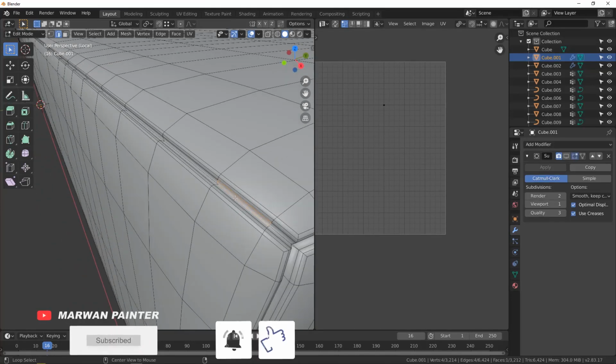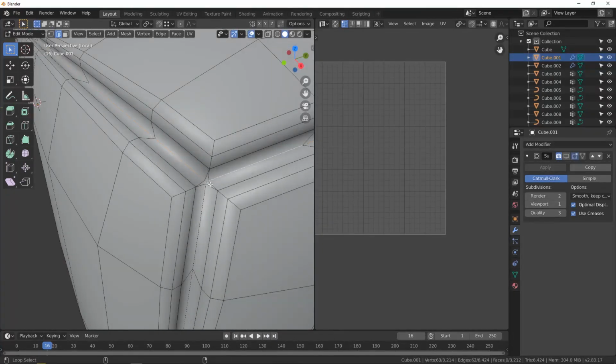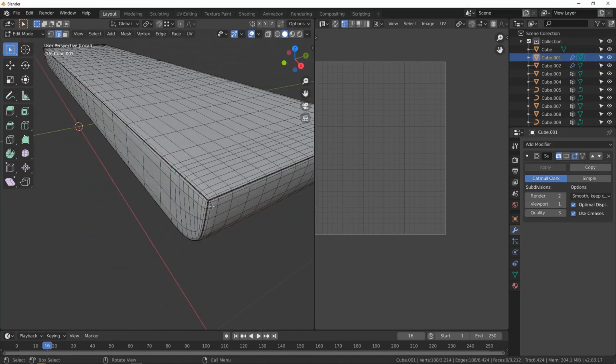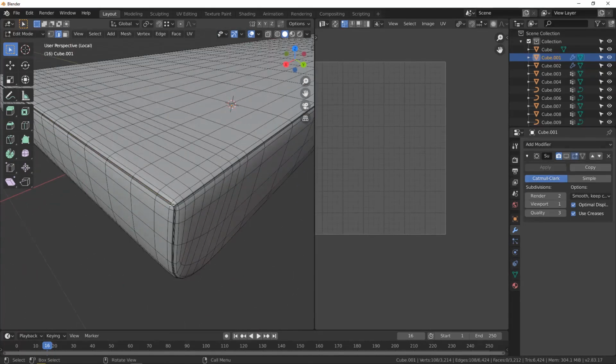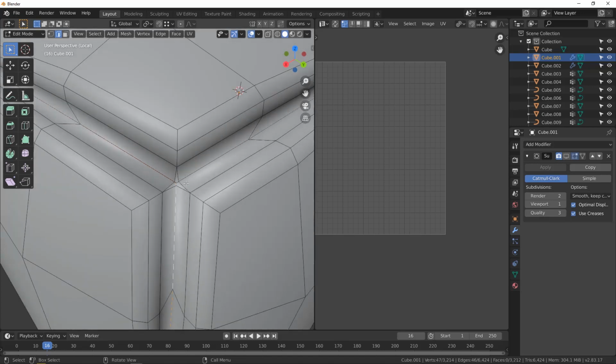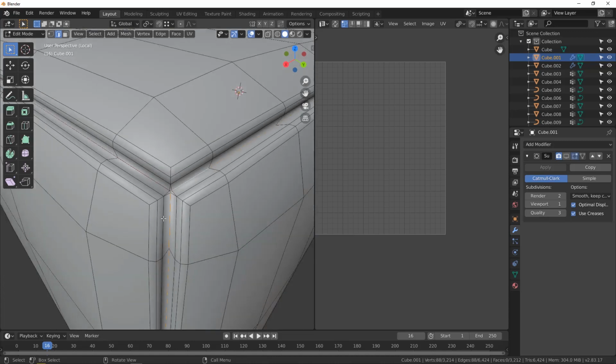make or add seams right here. Let's select this one, alt click and add seam, and on this corner and this one, and mark them as seam. When you select them, just mark them as seam. And there we go. Let's jump to the other side, this one, hold alt and grab this one, and alt shift and grab this, right click, mark seam,